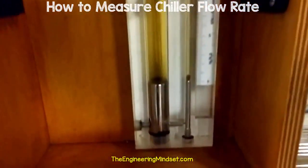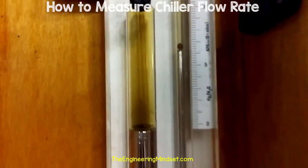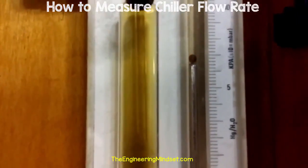When you do this, make sure you close the bypass valve very slowly and watch the little red ball begin to rise, as this can suddenly shoot up very fast. If it does get too high towards the top, then you should immediately open up the bypass valve fully to prevent the mercury from escaping. So just leave it a moment to settle down, and once it is stable, you can then take a measurement.